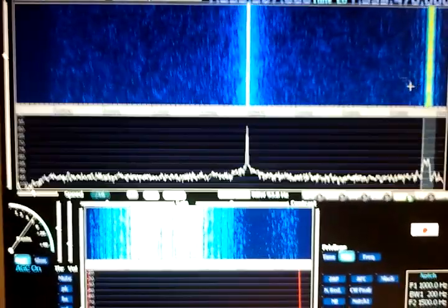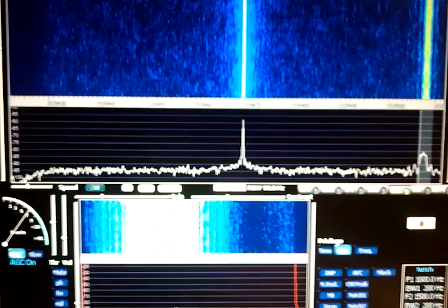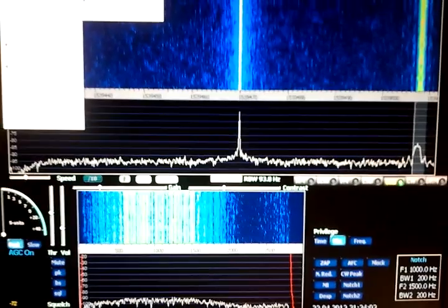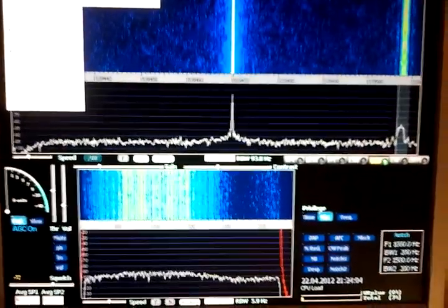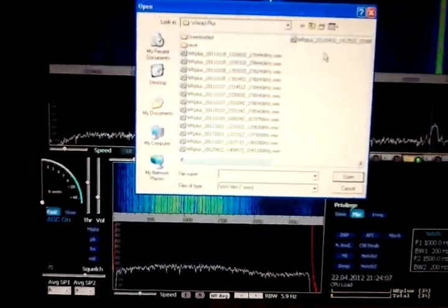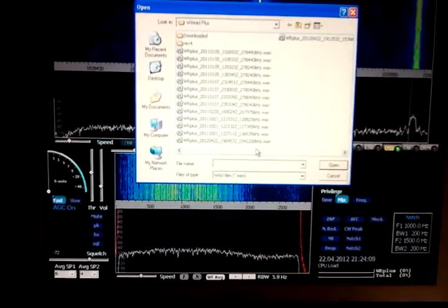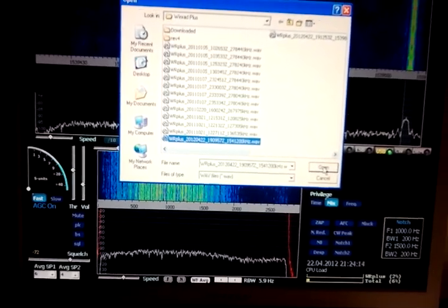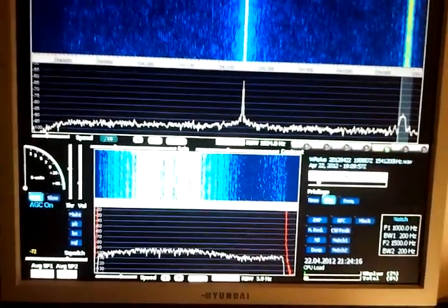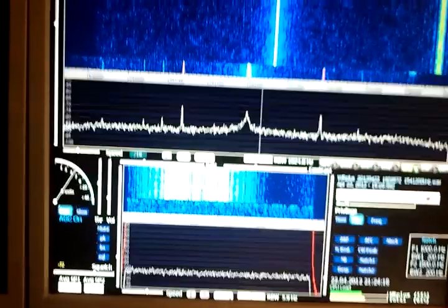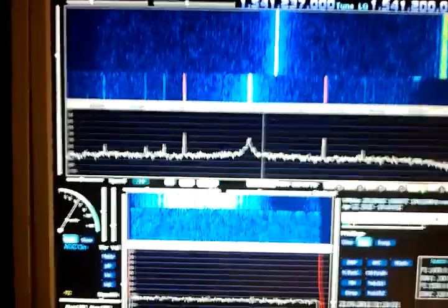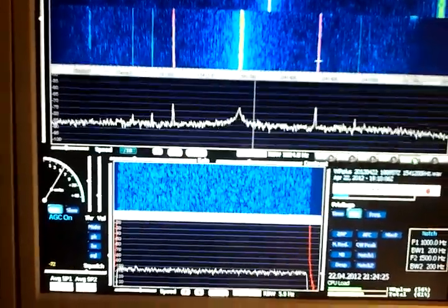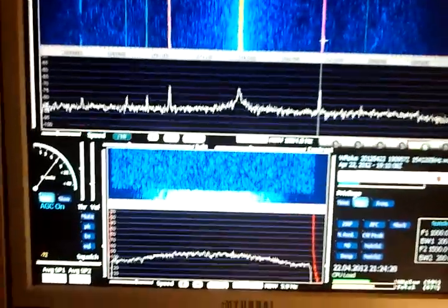But what is interesting now, I'm going to stop the Funcube dongle. In order to make it faster, and so I don't need to switch the antennas and the dongles back and forth, I'm going to load a raw IQ file, which I recorded just a few minutes ago, from the DVB-T stick. Here you have exactly the same frequency range, but now you see 1 megahertz bandwidth. So I'm going to tune the same signal, which is here, that I had before.